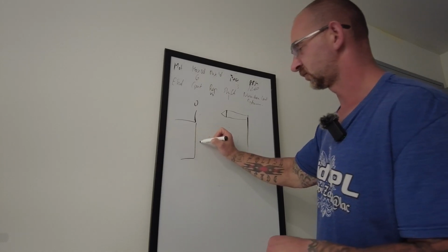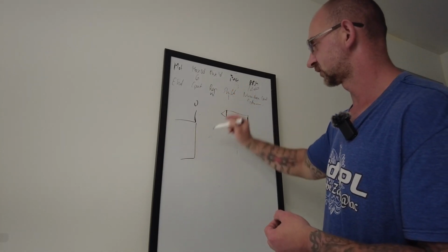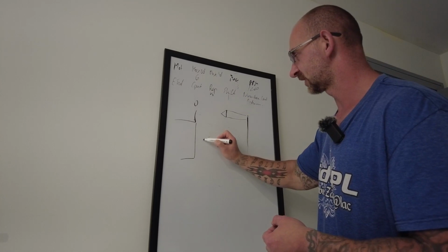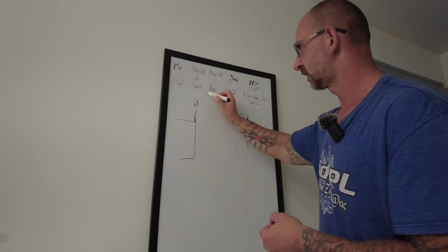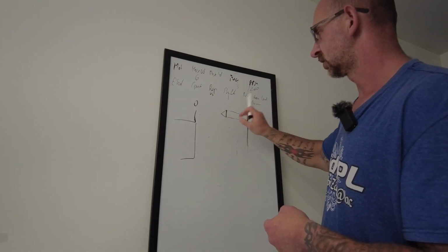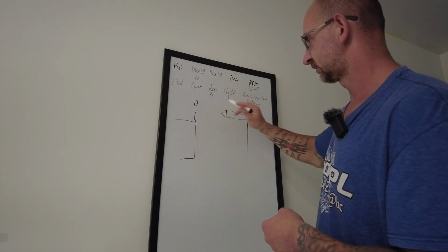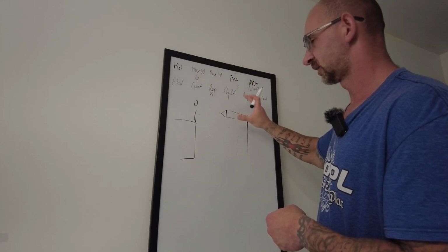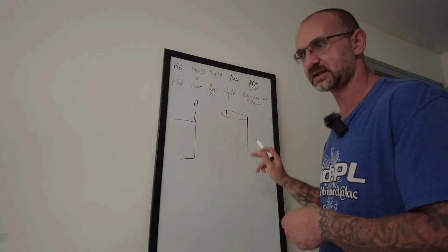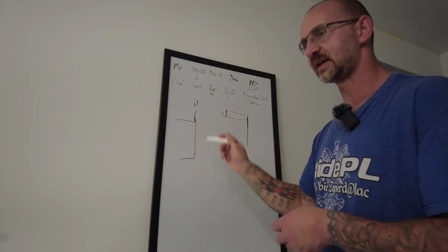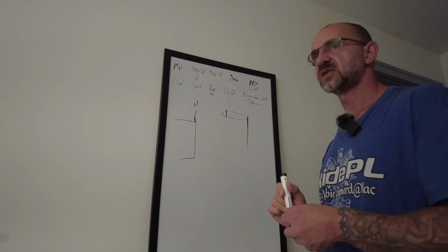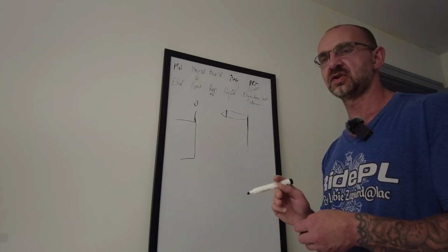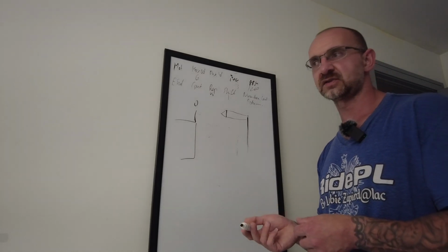If you have a face of 300, it's going to pull out 300,000. It's going to come up to the longest tool, which is the drill, plus the 300, and then it's going to rotate, come down, and engage another tool. You can also set this to 0, or you can set it to arbitrary.